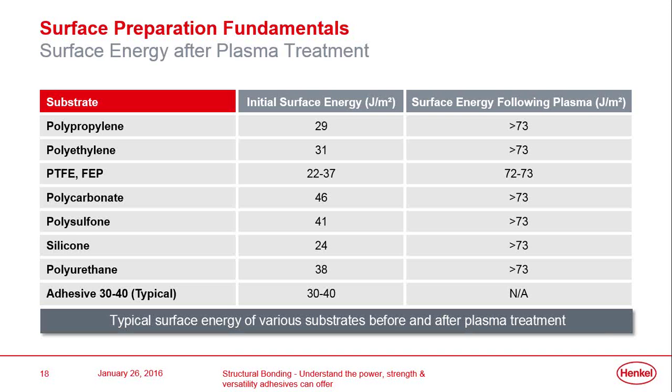And on the right-hand side, you can see the effect of doing some surface treatment. In this instance, it's plasma treatment. We get the surface energies up nice and high, and therefore we're able to bond to these materials even though they start off as non-stick materials.